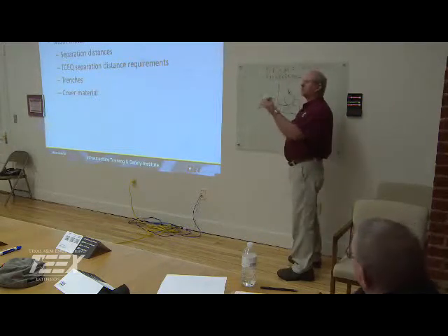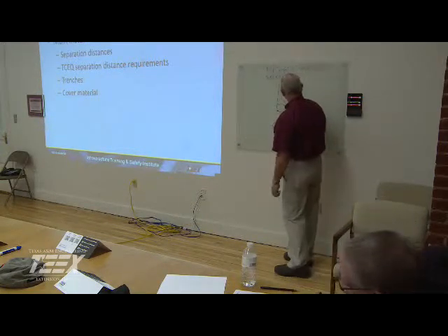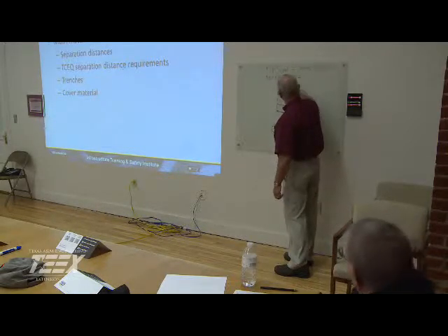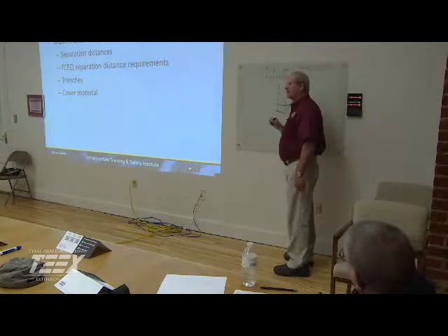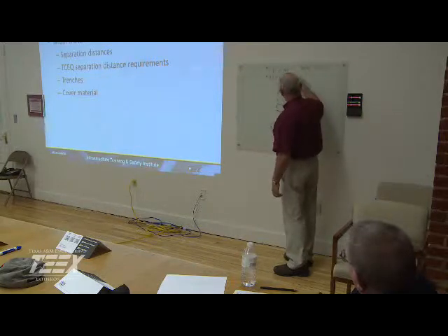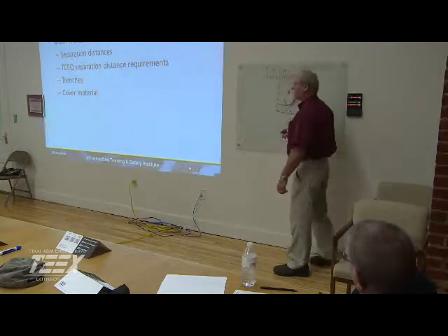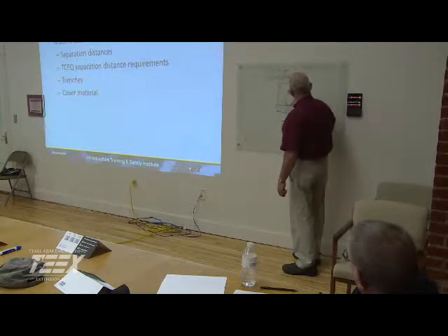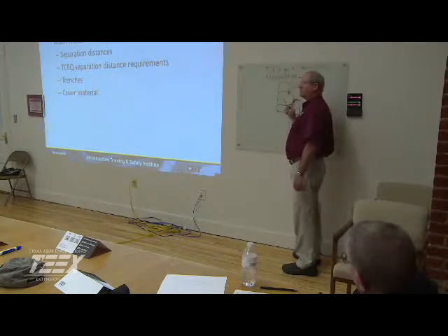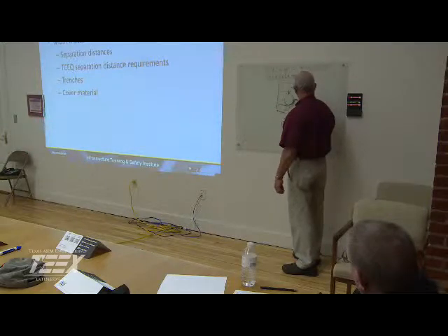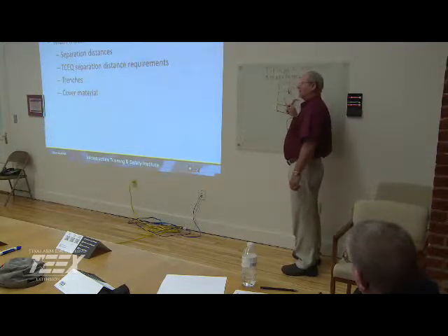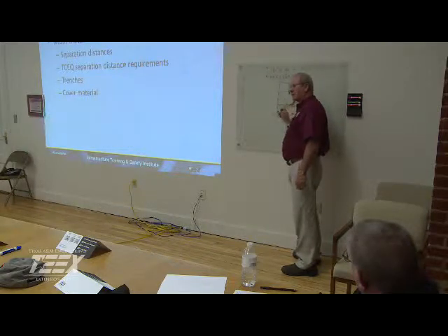We just pour it in real slow. Okay? We compress it so that we get a good haunching of the pipe, and then we're going to put it in 9 to 12 inch layers, compact it until we have a minimum of 12 inches above the pipe. Now, what they say is that you need at least 6 inches on each side for a total of 12. Now, it doesn't have to be completely centered, but it should be as near center as possible in your trench.